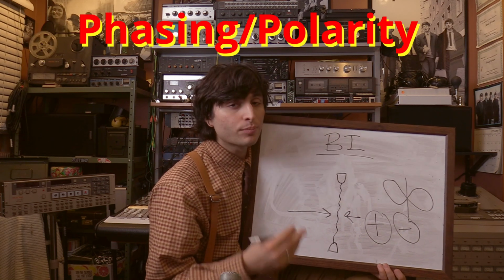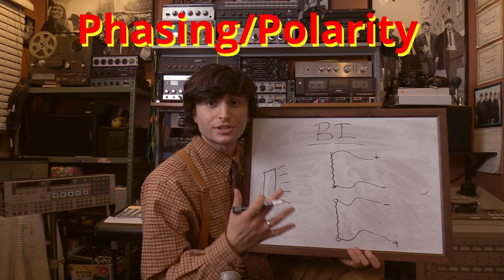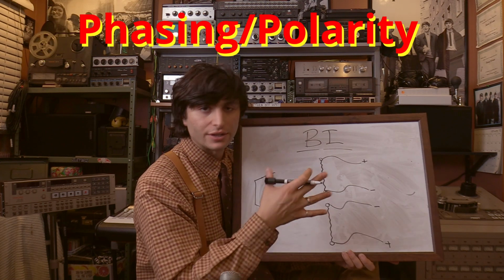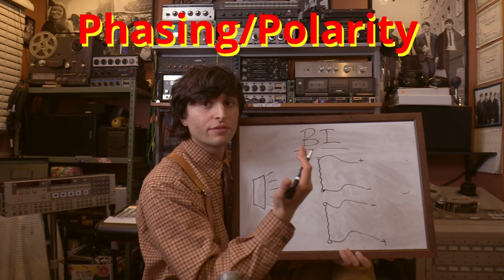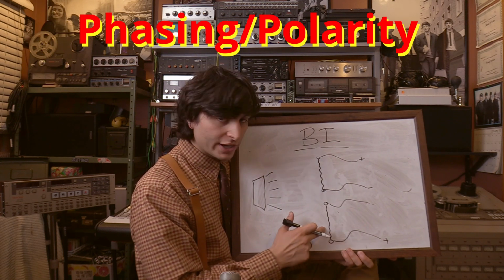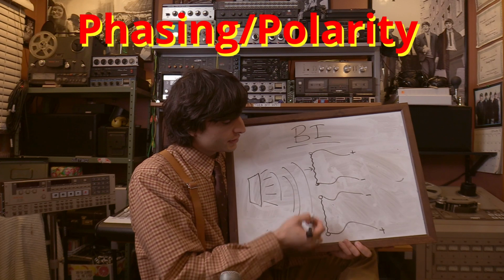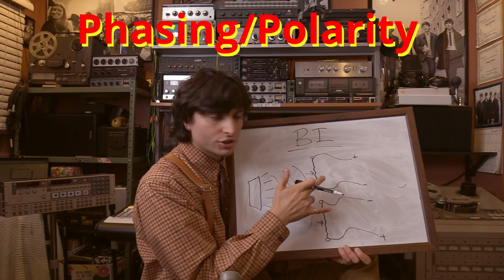Now, the reason this is important is because it affects the polarity of your microphone signal. So let's think of a worst case scenario of what could happen if you're not thinking about this properly. Let's say you had two ribbon microphones right next to each other in a stereo setup. And let's say for one of the microphones, you had the front of the ribbon microphone facing the sound source, but you accidentally put the rear of the second microphone facing the sound source. When the pressure sound waves from your sound source hit both of these ribbons, you're going to see a different polarity of voltages from each ribbon microphone.